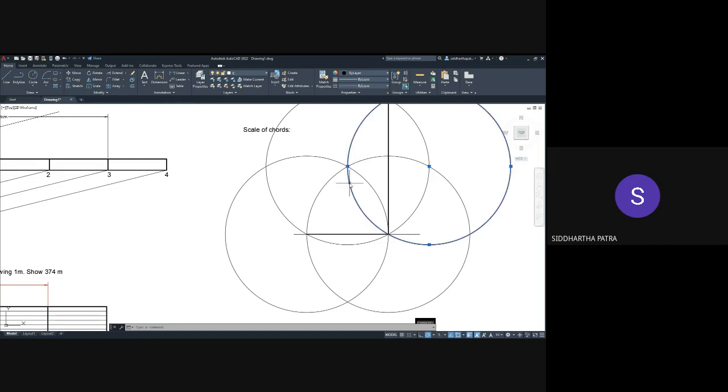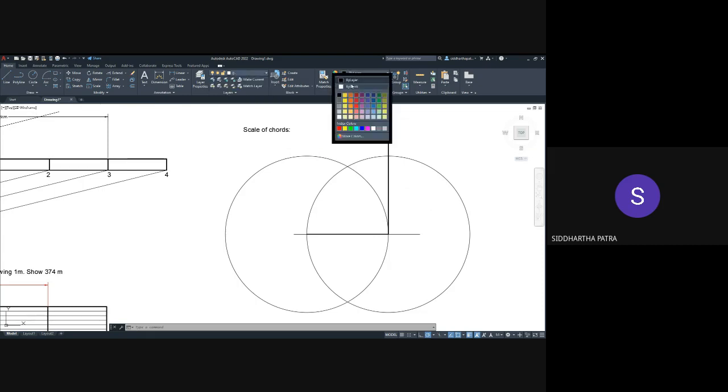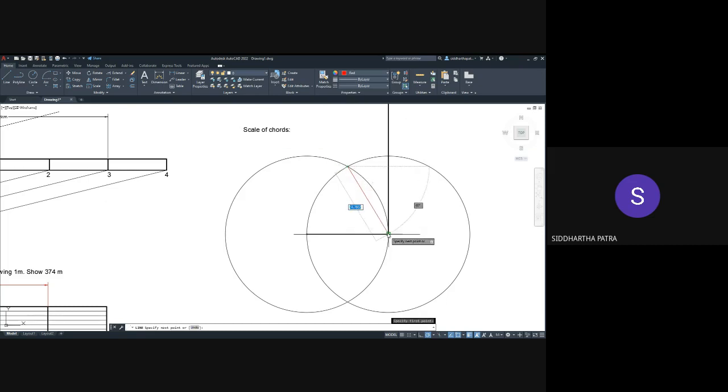and then you would want to divide it into three portions. Now that would mean that you need to divide this 90-degree angle into 30-degree, 60-degree, and 90-degree. Now you know how to get 60 degrees, so that one you have already got, and that is by drawing the circle, drawing a circle with the same radius, or circular arc with the same radius. So this much is 60 degrees.